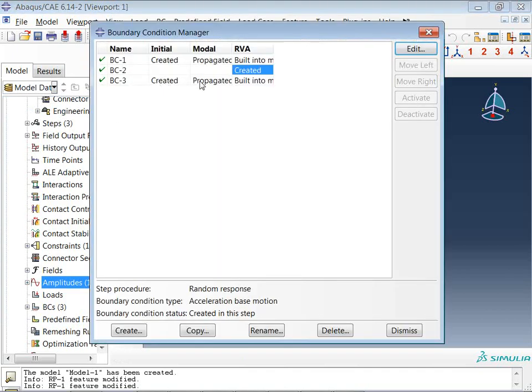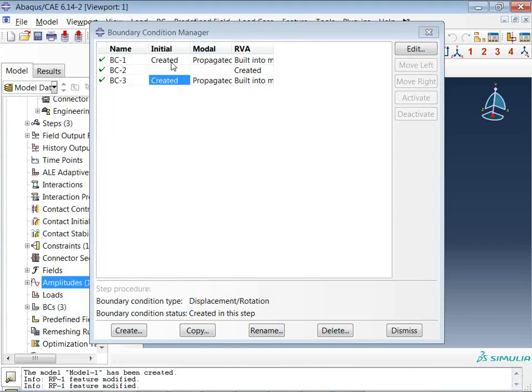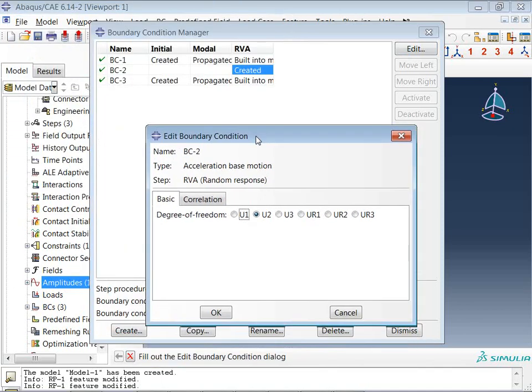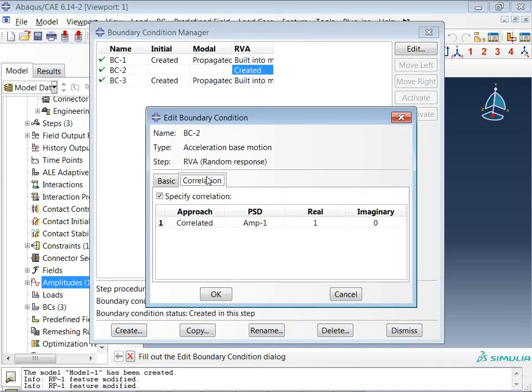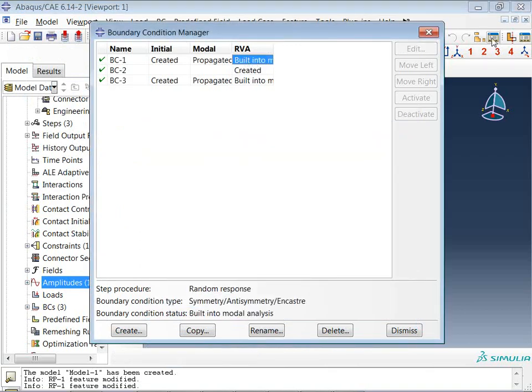Go to job, create a job, and then give a submit. History output. Okay, one more thing. At each step point, output is required. So here, for the first modal analysis, your default output would be your displacement. You can also call stress, that is von Mises, or your stress component would also be fine for the model.